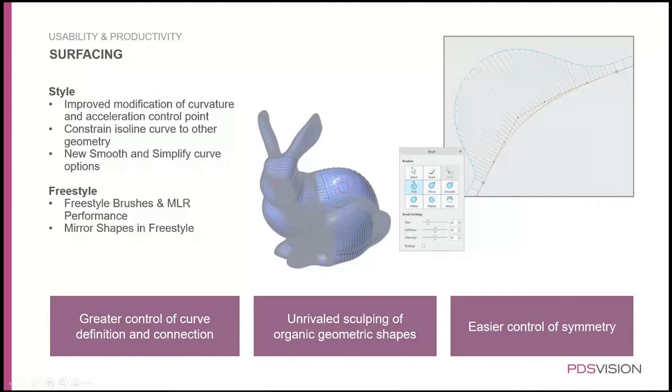Then we have Freestyle, which is this subdivisional modeling. In that subdivisional modeling, there's a possibility that you can have, let's say, an STL file or an OBJ file at the base of it, and then the system automatically maps this spline surface on top of it. And sometimes the results are okay and acceptable as they are, but sometimes you have to start modifying using those control points. But picking the individual control points can be a bit difficult sometimes.